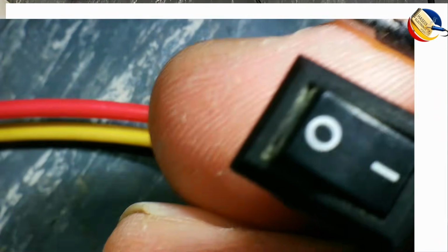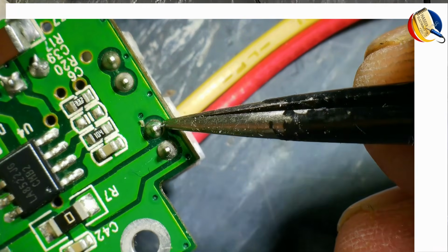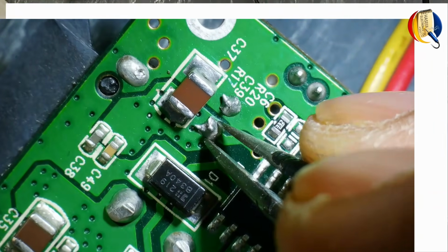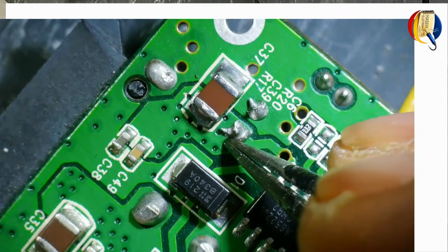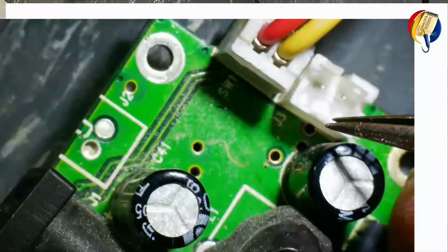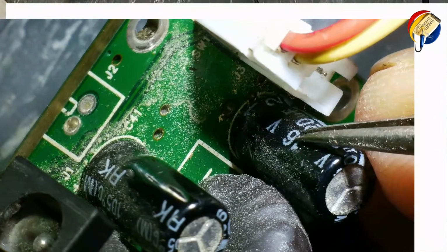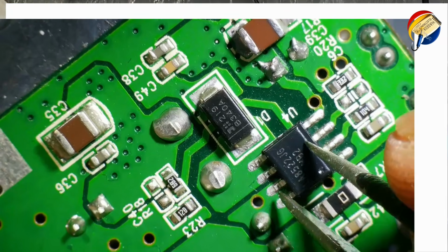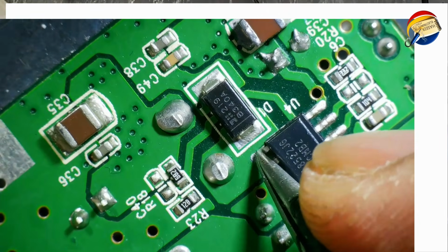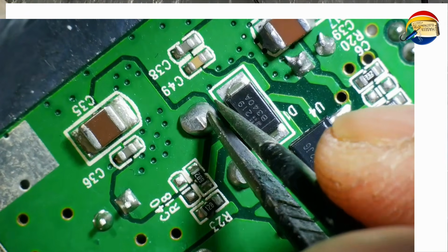When this switch is turned on, the voltage will pass from this point to this point. When this switch is on, that voltage will reach this point and it is connected to this capacitor. This and this. This end is ground. Here is the capacitor, that is this one. 220 microfarad, 16 volt. When this IC starts switching, it will provide switching from here to this point at 300 kilohertz. This voltage will pass through this inductor.